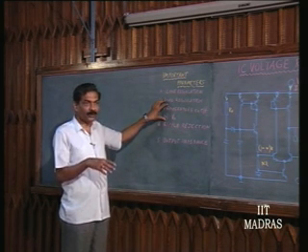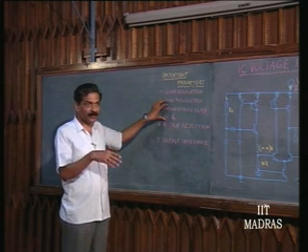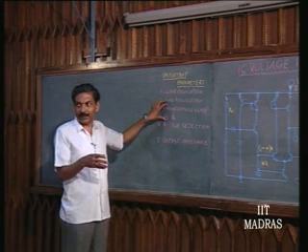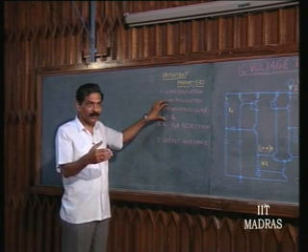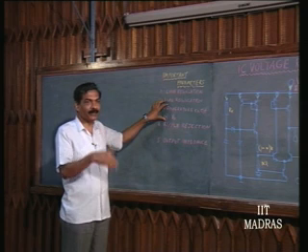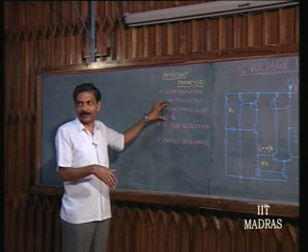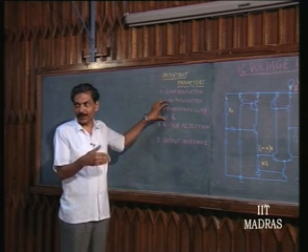What he wants you to do is select the resistors properly externally, so that V reference into 1 plus R2 over R1 will be the output voltage, and therefore, R2 and R1 should not disturb the already low temperature coefficient of your output voltage.